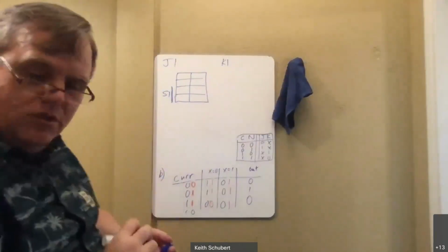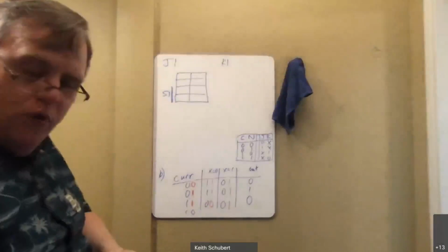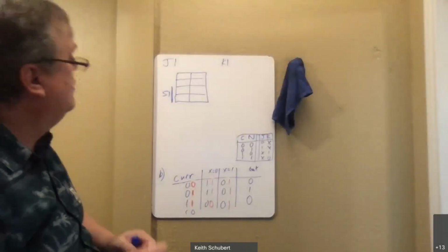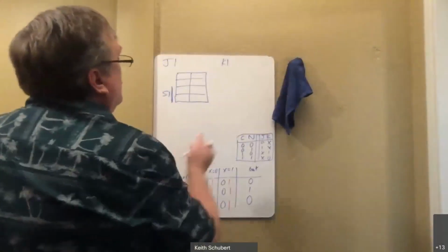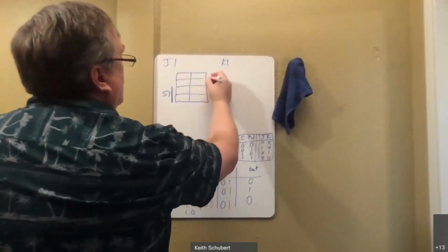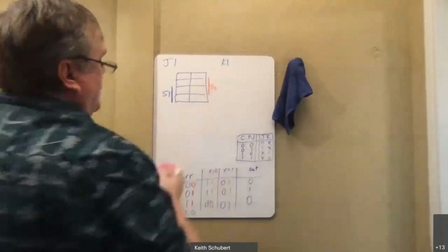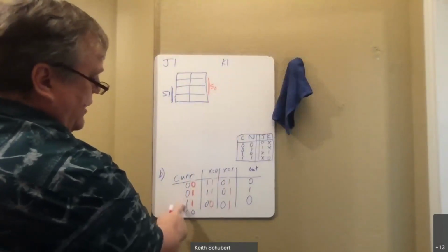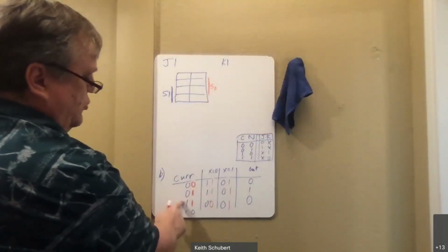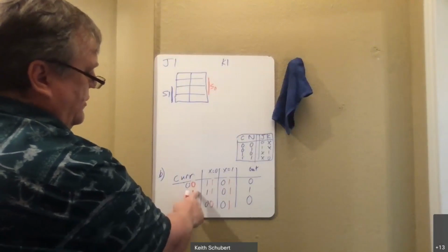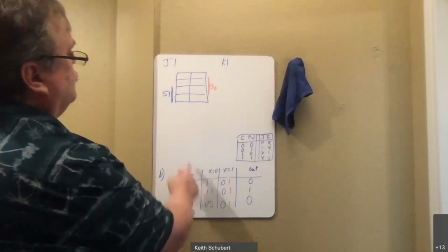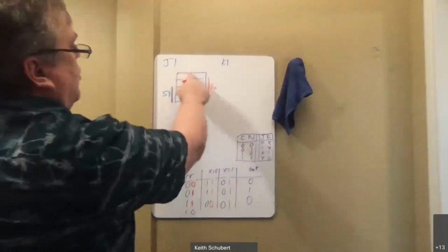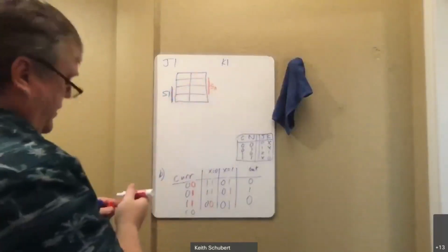Maybe I'll do this in red just to keep our blue-red convention going. This is state bit 0. That's the order they're in, right? The most significant bit is true on the bottom, and the least significant bit is true in the middle. And all of the next state stuff goes inside.